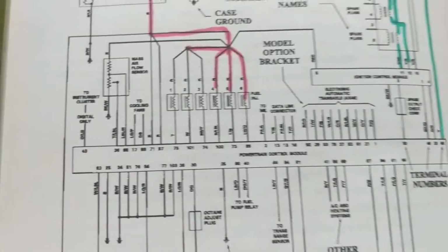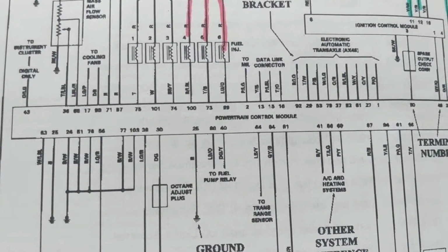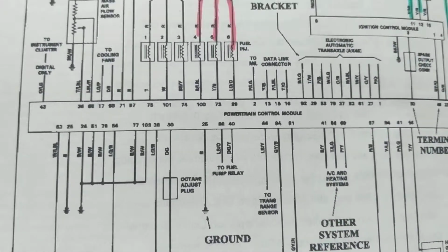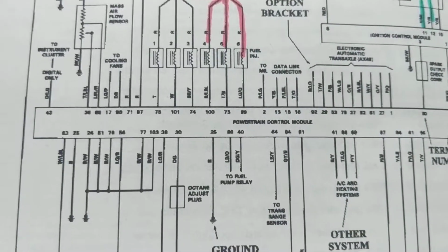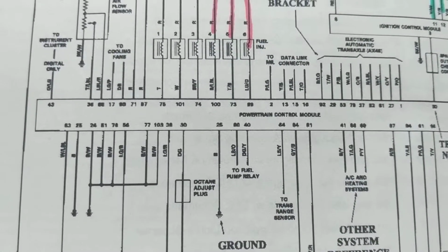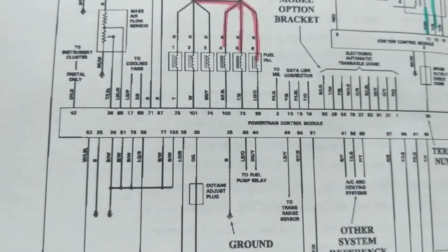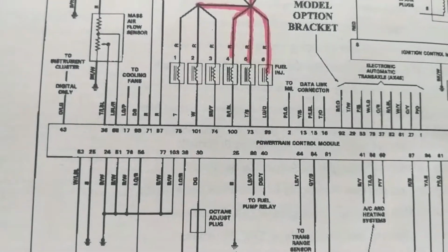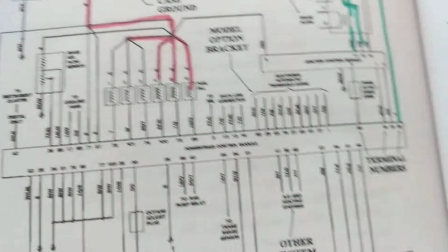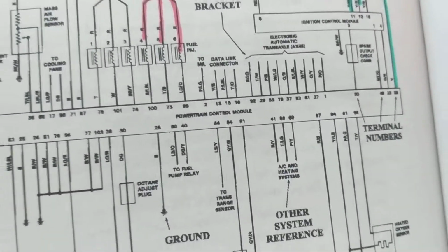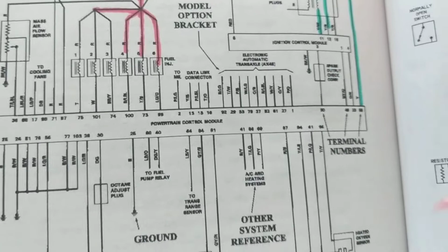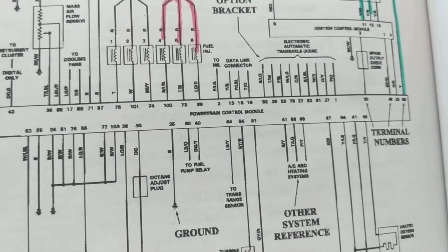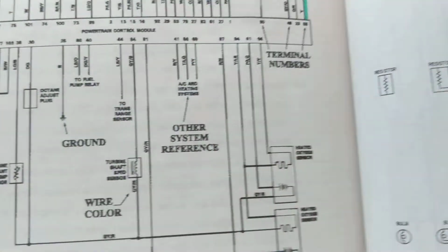As I stated in so many videos, the ratio of 14.7 parts air to 1 part fuel is what we're looking for. And the computer tries to adjust that ratio as best as possible to receive proper emissions. Proper emissions includes oxides of nitrogen, carbon monoxide, carbon dioxide, hydrocarbons, to get the correct pollutants. Anyway, so again, once you see a PCM, the computer, you expect to see inputs. You expect to see outputs. Again, what's inputs?